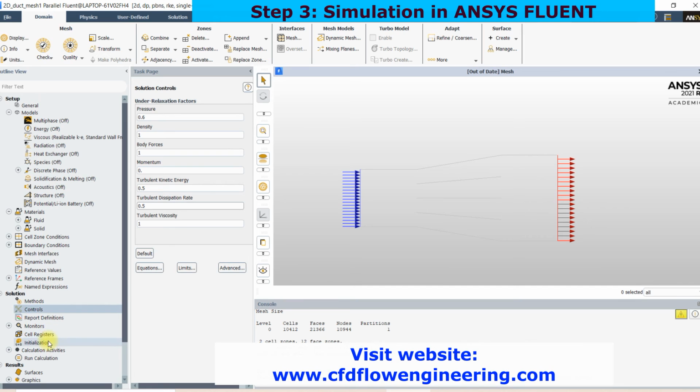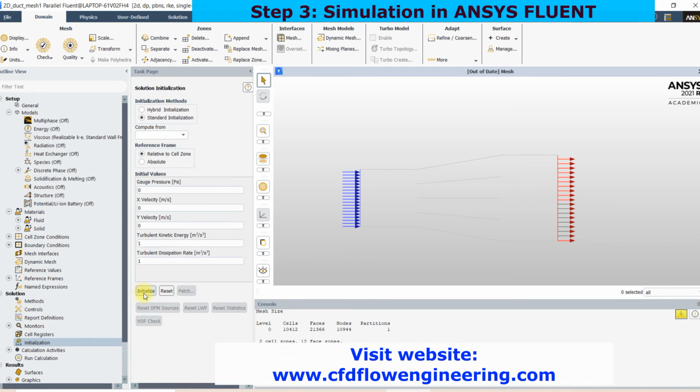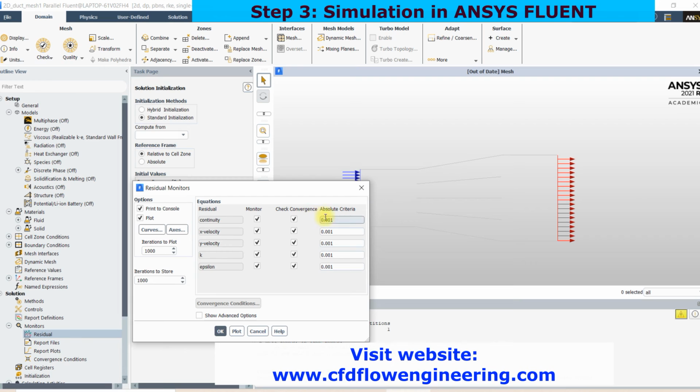Then after that, initialize, then residuals. Keep the residuals below 10 to the power minus 6 for all the variables.